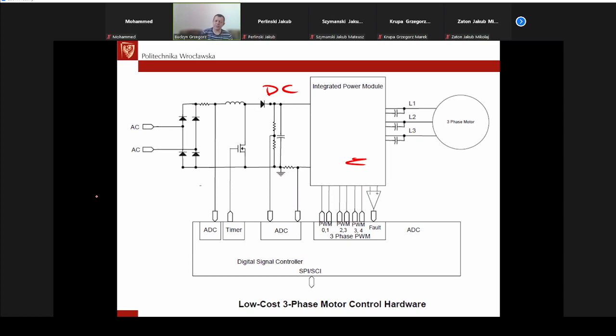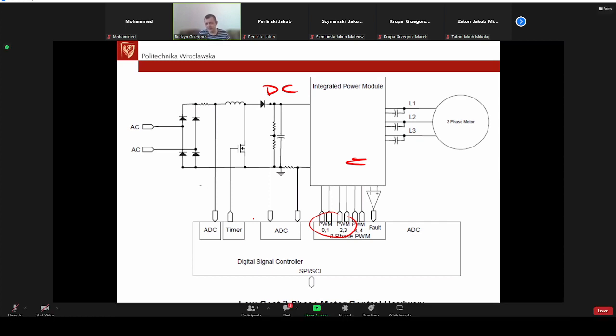And then the processor not only has to drive the lines, but more importantly, it has to measure the current flowing through the windings. So this is normally a really complicated task, because we drive the lines, depending on the configuration, but in general with PWM signals, and we need to measure at a particular time moment.